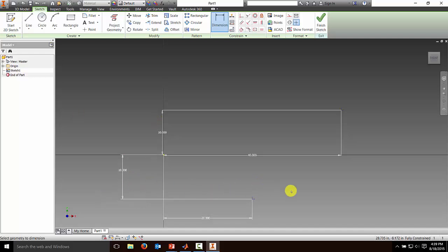Alright, now the reason we did this was so that we could create a circle that has a diameter between these 2 points. So let's do that. Let me go ahead and make a circle. I'm going to put my circle as close as I can to the x-axis and let it contact the point, and you can see that it's telling me it's going to create a constraint, making sure that circle is touching that point.